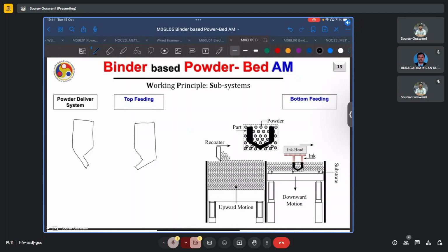And we can clearly see how that would be useful in an electron beam melting process because we have to maintain vacuum over that entire chamber. If the size of the chamber is very large, achieving vacuum will take a very long time, as well as there will be many vulnerable points from which leakage can occur and that vacuum can be disturbed.